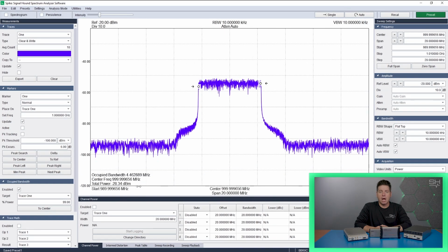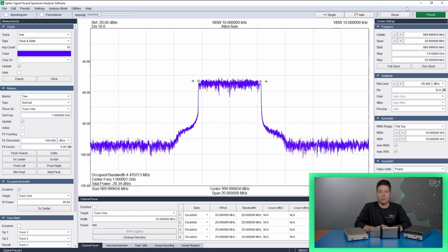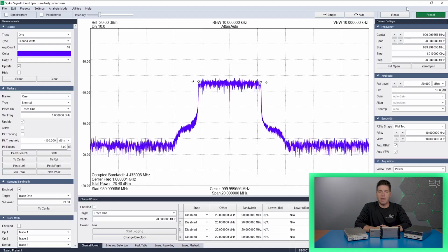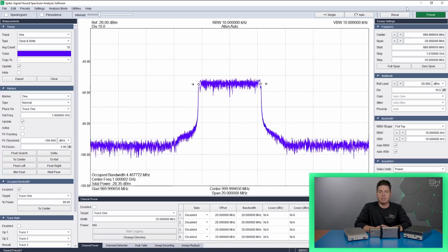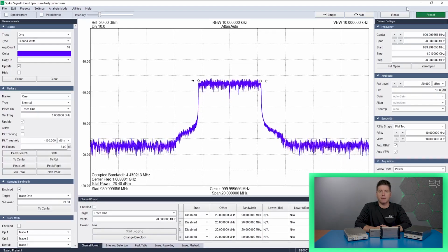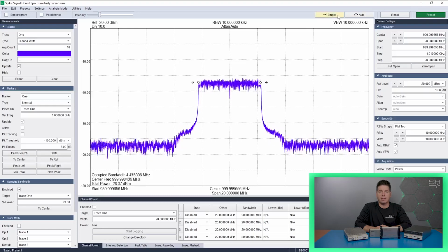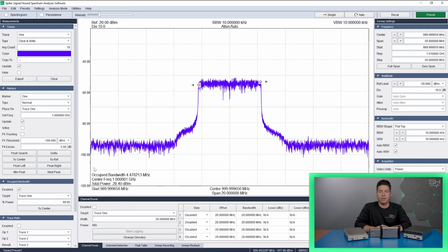For example, a communication standard, 3GPP, may describe occupied bandwidth as the bandwidth that contains 99% of the total integrated power of the signal centered on the assigned channel frequency. Additionally, this bandwidth may be limited to a few megahertz, and any transmitter technology violating this requirement of the standard would fail to comply. An approximation of the center frequency can be achieved by finding the center point between the highest and lowest frequency of the occupied bandwidth.